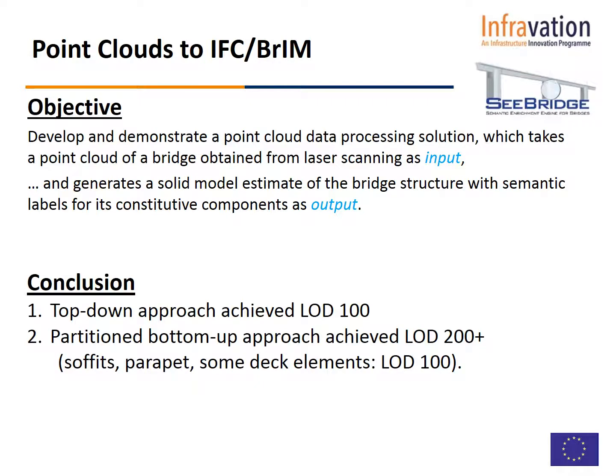However, we have actually achieved our objective, which is to take this point cloud input and generate solid model estimates of the bridge as output. And not only that, but also have them semantically labeled. Our top-down approach achieved the LOD 100, and the bottom-up approach achieved an LOD 200 plus, which means that we've effectively created this algorithm that now allows us to do the remaining parts of our sea bridge pipeline.